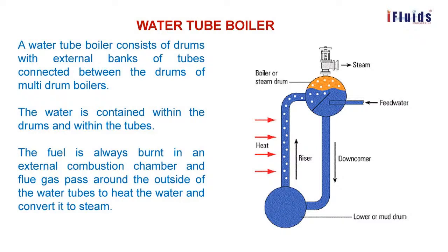This circulation takes place while heat is continuously supplied by the combustion burners, and the flue gas passes over the tubes to raise the temperature of the feed water so that it becomes steam. In the downcomer it is completely water, and when it rises through the riser to the steam drum, it is a mixture of steam and water. Here it is separated.